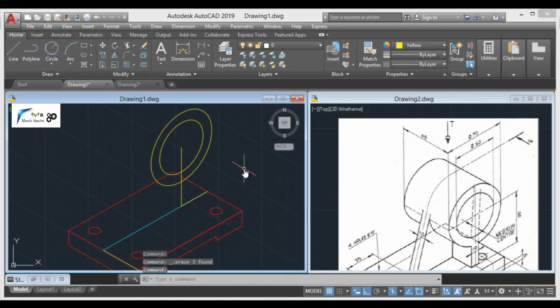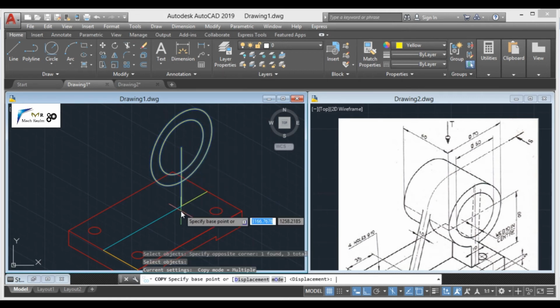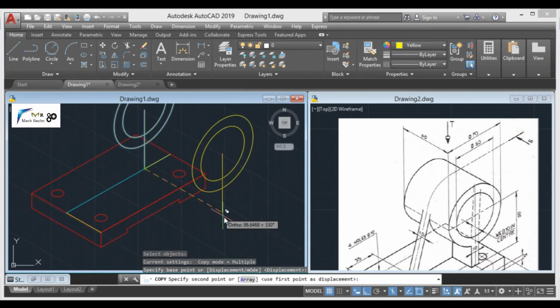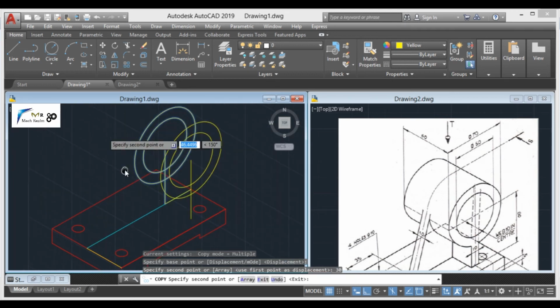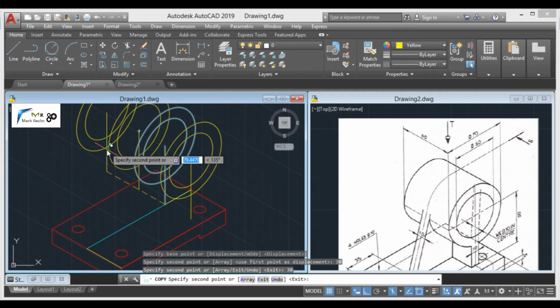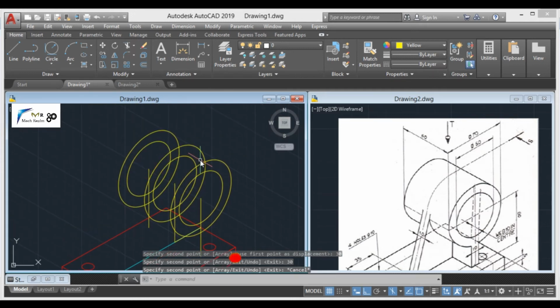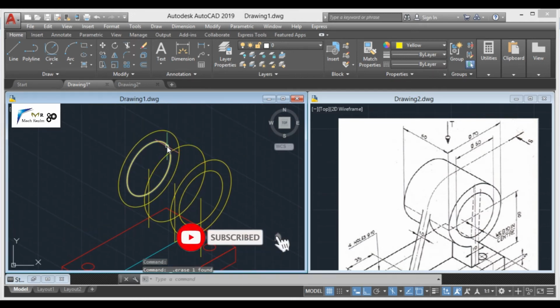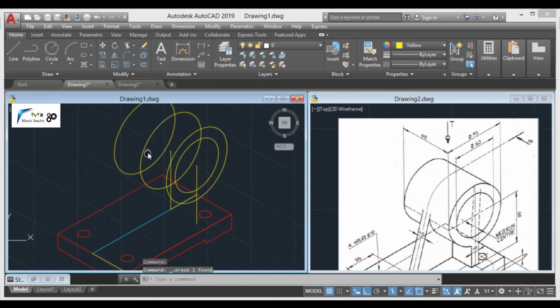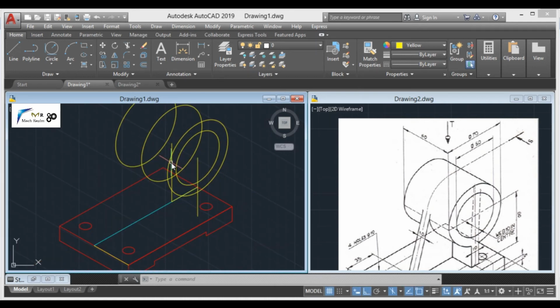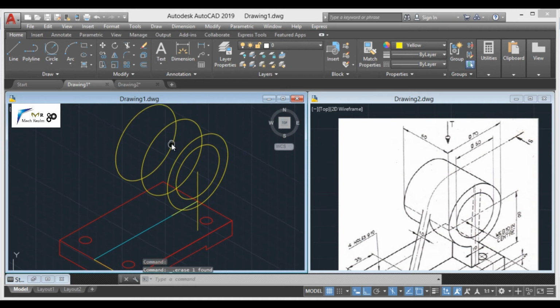Now let us copy it. So simply let us copy the two circles, from this point in this direction at a distance of 30 mm and towards back at a distance of 30 mm. Clear? So let me erase the inner circle and this one of inner circle. Clear? And also this line. Understood? Let me also erase this particular line, that is a center line.